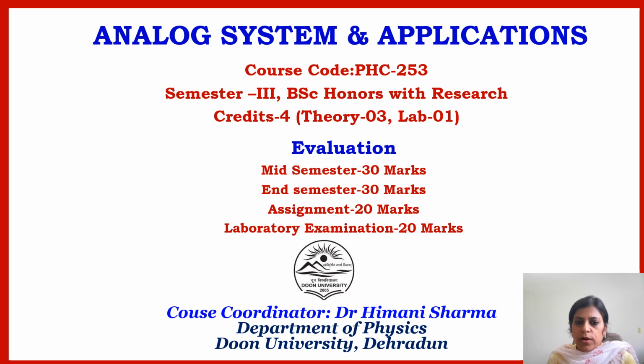Now, in our second module, we are going to study about the PN junction, their VI characteristics, and their various applications. If we talk about PN junction, it's basically a crystal diode in which the current conduction takes place only in one direction. So these PN junctions have a variety of applications. For example, they are being used as rectifiers: half-wave rectifiers and full-wave rectifiers. They are also being used in solar cell applications, and they are also used as light emitting diodes.